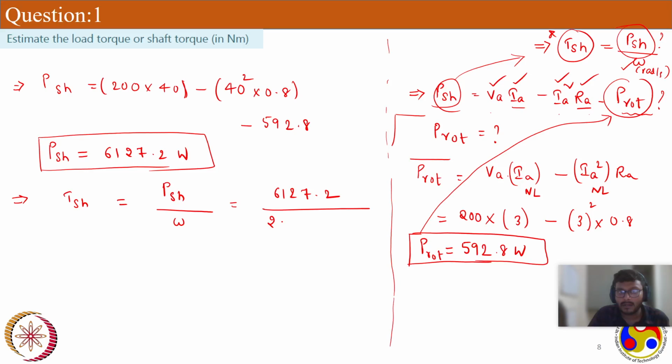Here my output power is net mechanical power. Input power is again VA IA plus VF IF. So we discussed that as well, and then we discussed how torque and power can be calculated from those relations, and we justified with the basic derivation we did 2 weeks before with the force equations and conductor. We took the individual conductor force and arrived at the torque. So we again arrived at the same equations from this kind of analysis as well.